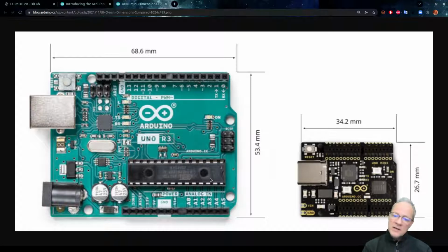Besides that, it has a number of peripherals, including an analog to digital converter, so that we can attach all kinds of sensors to it. For example, we can attach a microphone to it through a little amplifier, through these A0 till A5 pins. So all in all, we have 6 analog ports that we can hook up to this controller, right?